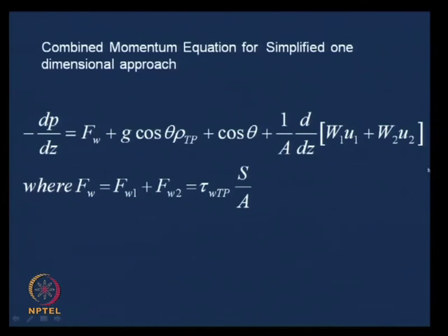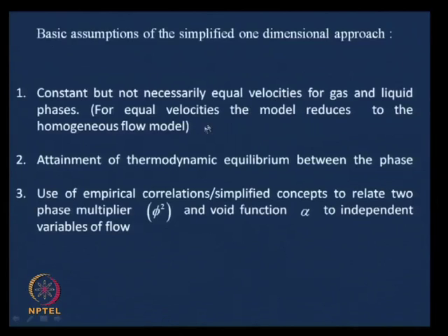If you observe this form of the equation and the homogeneous flow model we had developed, the only assumption we relaxed here was that the two phases are allowed to have different velocities. Other than that, this expression is identical to the one we derived for the homogeneous flow model. Accordingly, we had laid down the basic assumptions of the simplified one dimensional approach, and then in order to develop certain